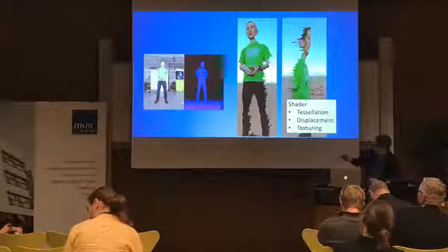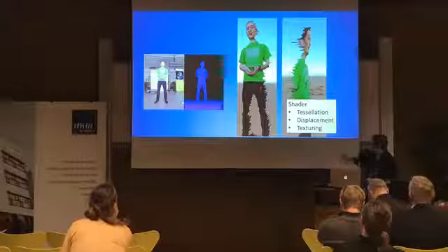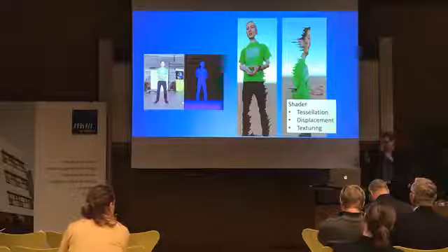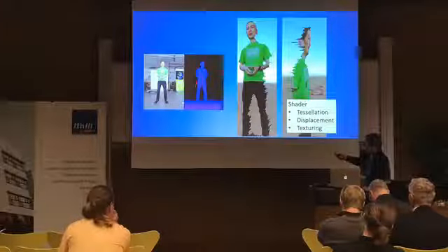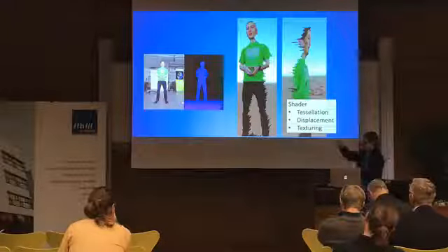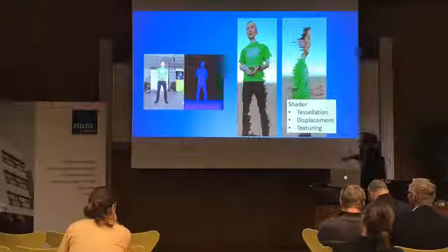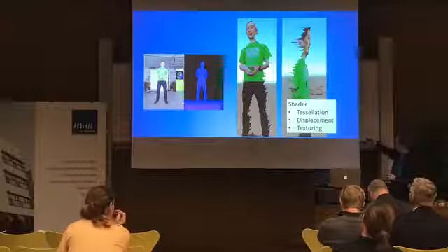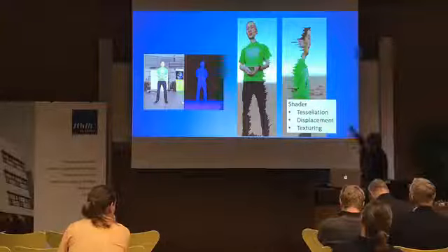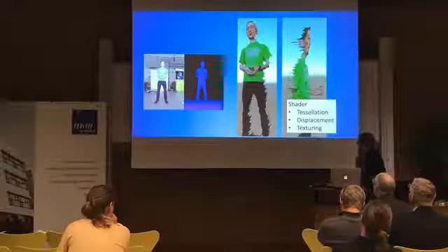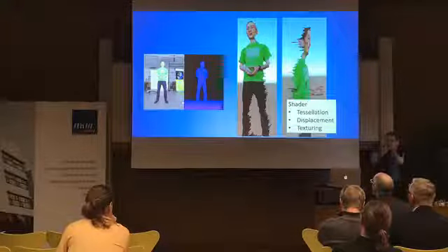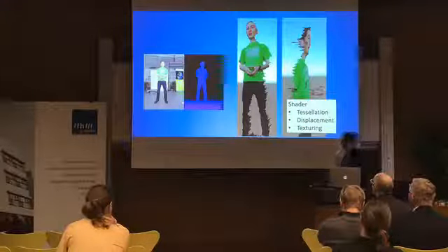So the color image was used to color the vertices, the points of a mesh. And the depth image, this is the red color layer of this image, was used to deform the object. It was first tessellated, so subdivided, to deform this image. And the black color here shows where this object is invisible, so the transparency.